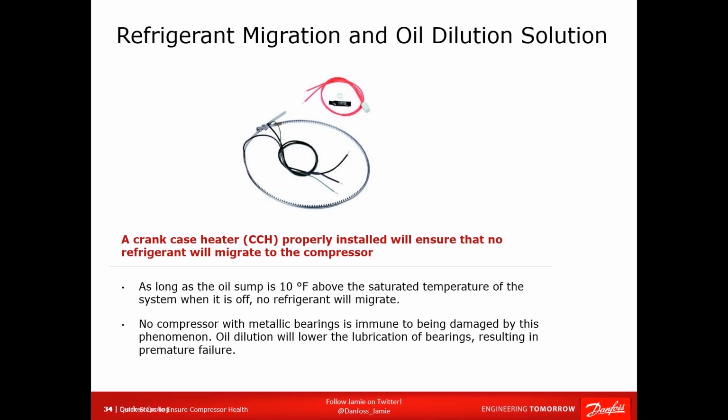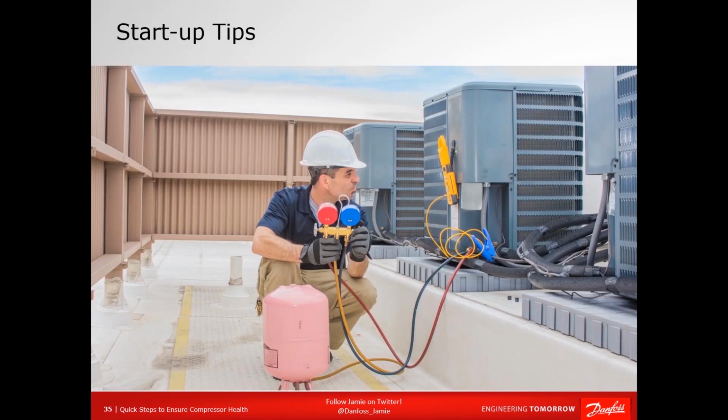But anyways, here we have a couple different kinds. The bottom is a belly band that wraps around. The top one is an insertion type. It would go into one of our MTZ or MT or NTZ compressors. It is self-regulating voltage-wise, anywhere between 100 and 600 volts. You also have the pancake or diaper type that fit on the bottom of the compressor. They also help reduce noise, and they're very efficient.